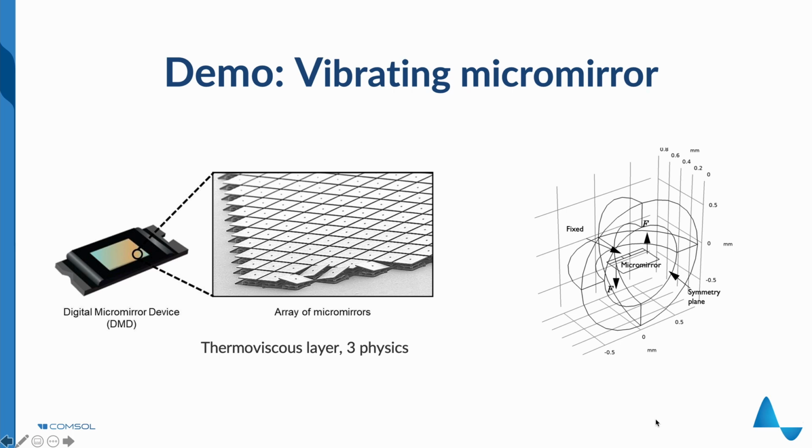The model combines the shell interface, the thermoviscous acoustics frequency domain interface, and the pressure acoustics frequency domain interface. So we are going to use 3 different physics interfaces to model such a device here. The 3 physics interfaces are set up and combined using multiphysics coupling, one for the acoustic thermoviscous acoustics and one for the thermoviscous acoustic structure boundary connection.